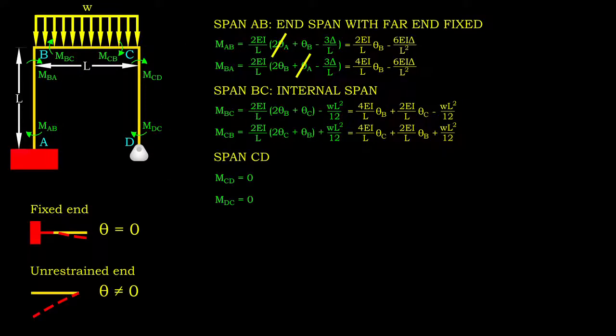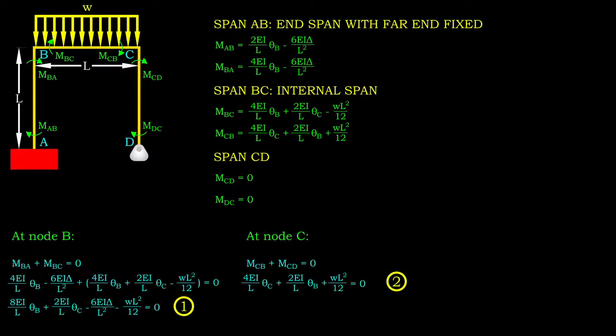By checking the boundary conditions of members, we can conclude that only point A does not allow rotation. Therefore, we proceed with eliminating theta A and remain both theta B and theta C in the equations. We are good to simplify the equation again at this point. Our slope deflection equations consist of 3 unknowns, namely theta B, theta C, and delta.